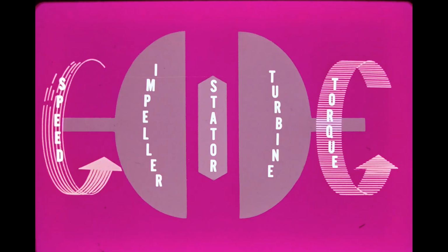Under these conditions, with the load on the machine causing the turbine to slow down, the turbine will be rotating very slowly in comparison with the impeller. But because of the tremendous impact of the fluid on the turbine blades, the turbine will be transmitting tremendous power or torque to the rest of the drivetrain. In fact, because reaction torque is being created, the turbine will actually deliver more torque than the engine alone can develop. In short, engine torque has been increased or multiplied.